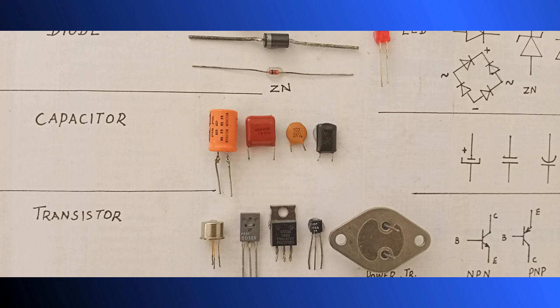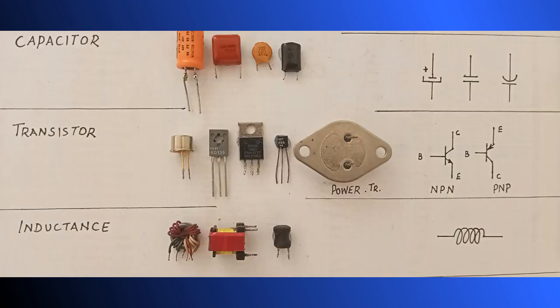The first one you see, the orange colored one, is a polarized capacitor. In the polarized capacitor, on the side there is a small minus sign printed on it with a black arrow mark, and I will show you also a little later. That denotes the minus. The opposite side is the plus. But in non-polarized there is no symbol. For all these components, first I am explaining the component, and then one by one I will explain the functionality, which is very important.